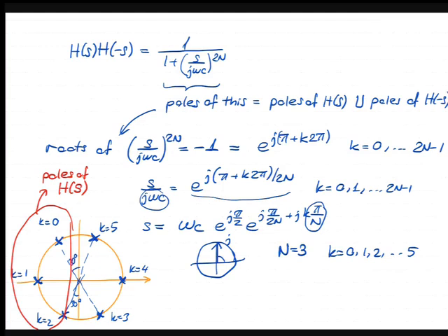If you have higher degrees, there's a formula. You still have poles on the half circle. Stability restricts us to the left half plane. So it's not the whole circle that's relevant, only the half circle to the left. Okay? So when you look at the poles of Butterworth filters, they're always on a half circle in the left half plane. And they start with pi over 2n degrees from the imaginary axis, and they go by pi over n. So you can increase the order as much as you wish.